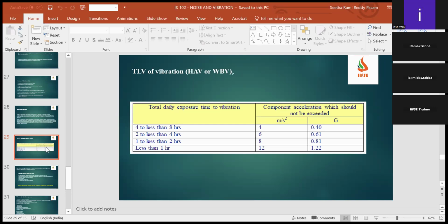No, we don't have any such standardization. Basically, as you said, it is very true. Whenever any such issues come up, we check the complete foundation of the machine or the installation, and we check the vibration dampers. They install the vibration dampers, adjust accordingly, and then check the vibration level. As you mentioned, if it comes to the acceptable level, then they give a go-ahead. Otherwise, they recheck the condition. But there is no such standard for each installation; we always refer to the OEM recommendations.